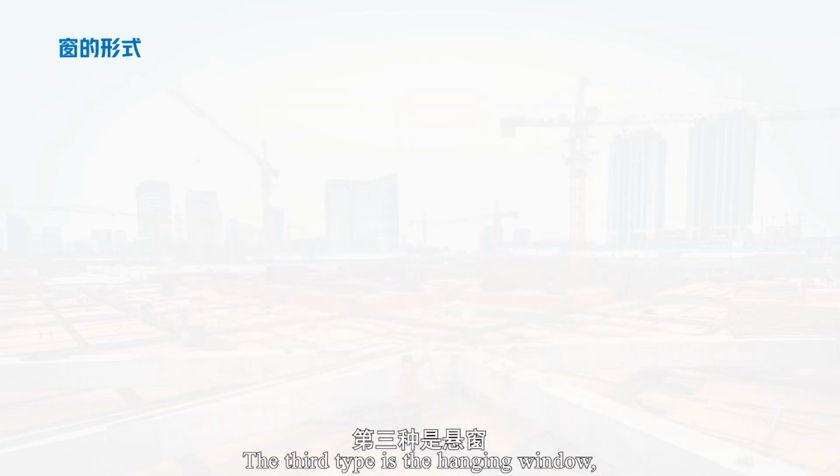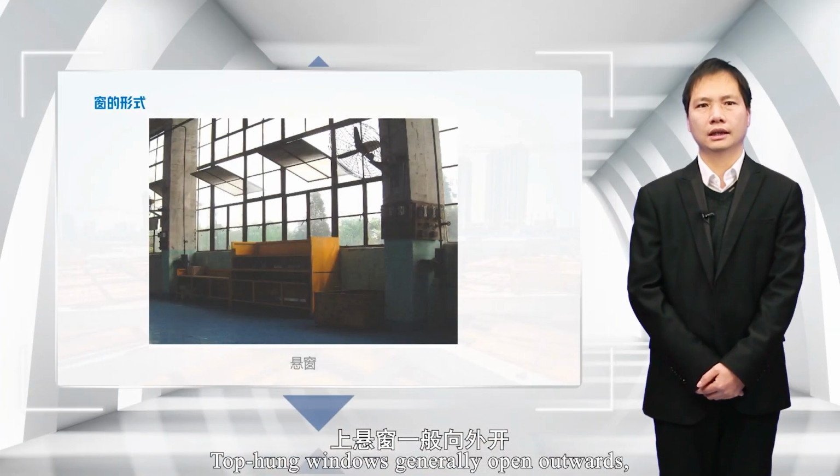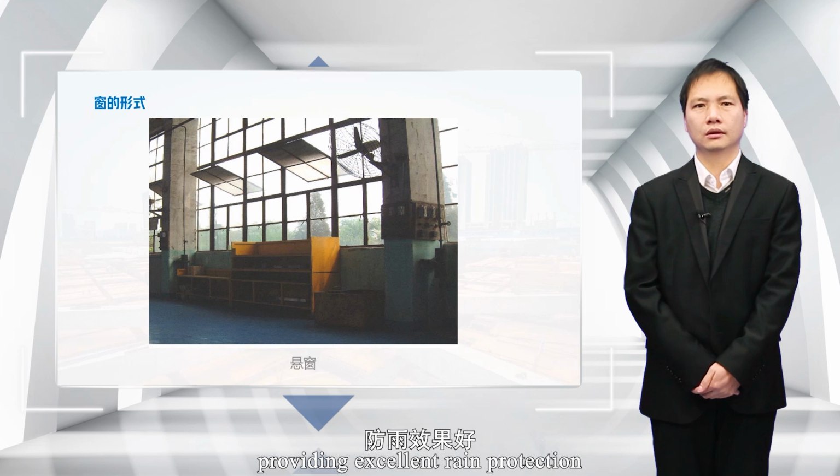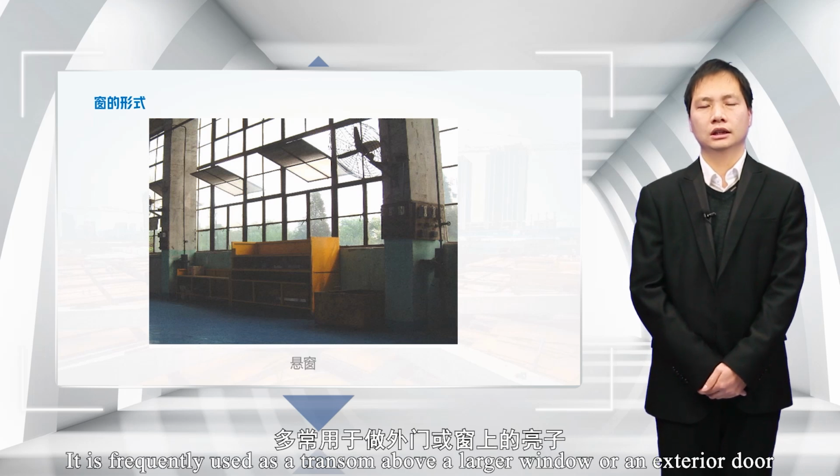The third type is hanging window, which can be categorized into top-hung, middle-hung, and bottom-hung varieties. Top-hung windows generally open outwards, providing excellent rain protection. It is frequently used as a transom above a larger window or an exterior door.